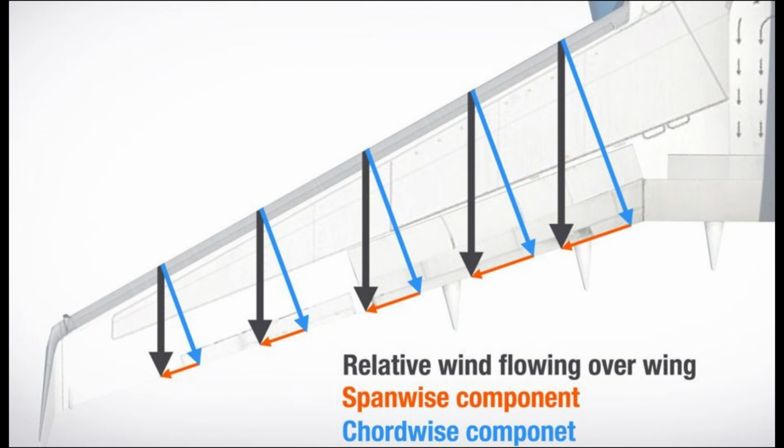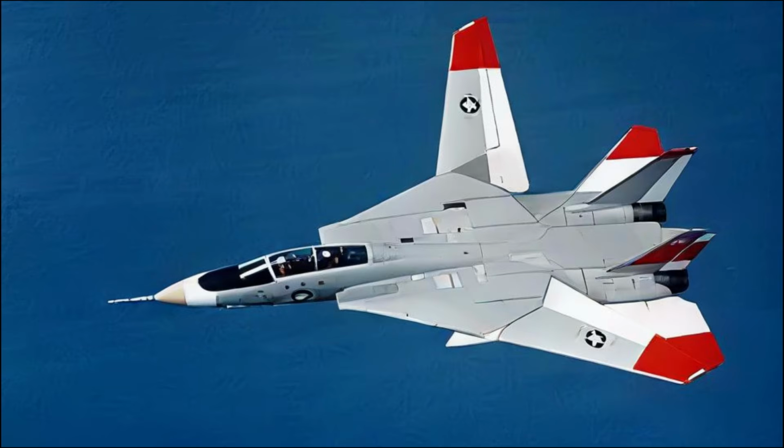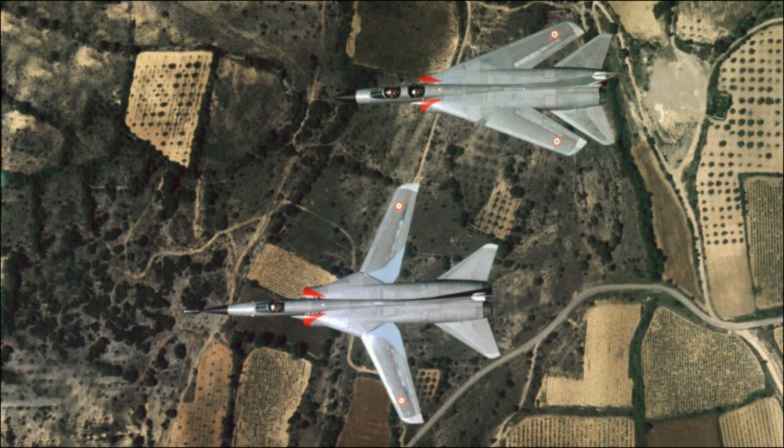Jones's contribution also influenced how engineers thought about stability and control. At high sweep angles, airflow tended to move outward along the wing, increasing the risk of tip stall and loss of aileron effectiveness. This forced designers to consider wing twist, airfoil variation along the span, and control surface placement more carefully. These refinements deepened aerodynamic understanding rather than simplifying it.